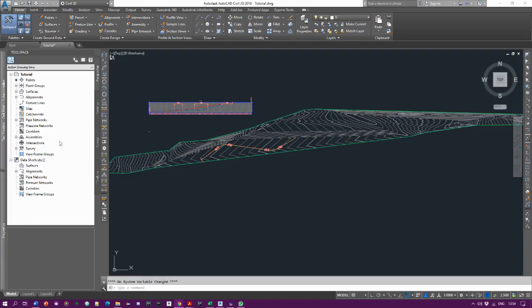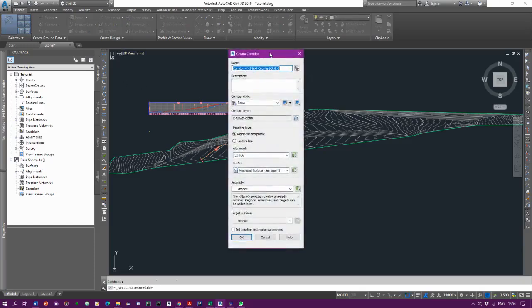design. Now, to create the corridor, we would simply click on the corridor command. When you click on that, this dialog comes out that enables you once again to name your corridor. And you can set other parameters for this corridor, including the horizontal alignment, the profile we have designed. In this case, let us use VA.